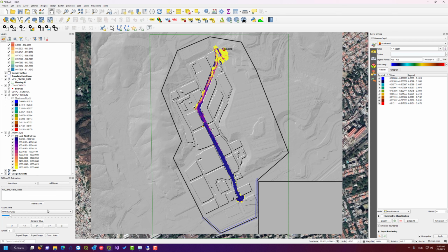So the nighttime, as you can see, the oil is cooling down. Most likely this is occurring in the middle of the night, and then later down the line, nearing the morning and noon time, the temperature will go higher and the yield stress will lower and allow the oil to flow some more.